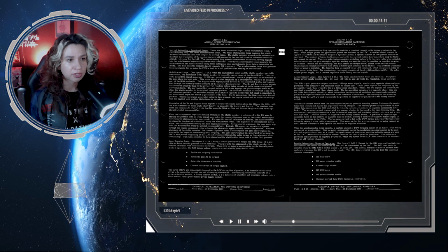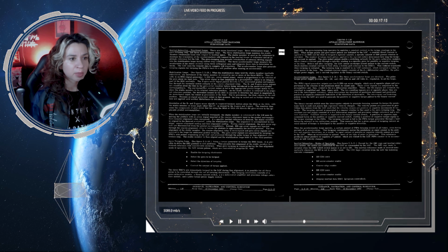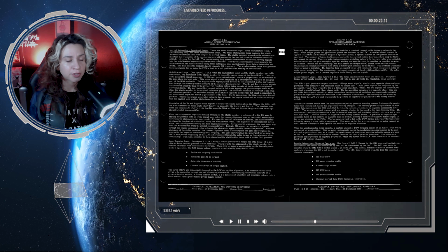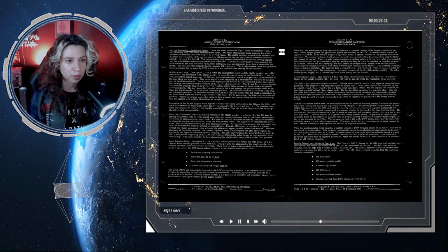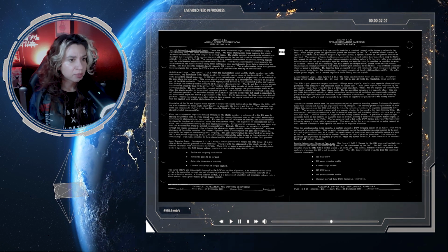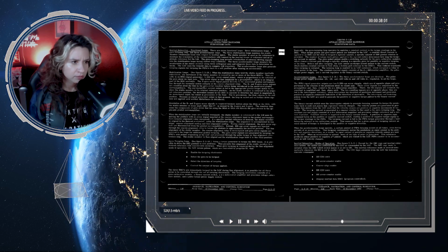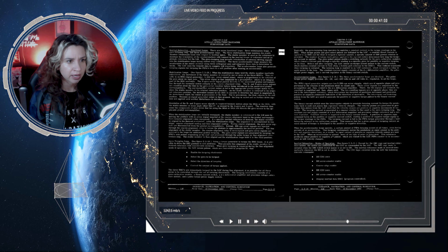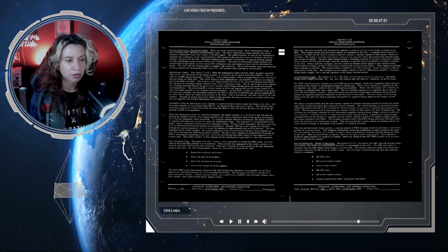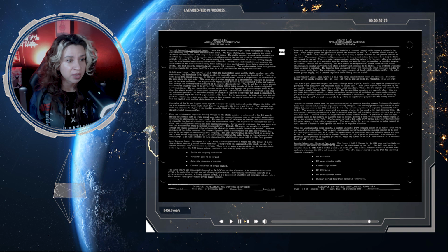The velocity pulses are generated by providing data pulses from the LGC, such that the velocity outputs are positive or negative increments of velocity. The torquing current is generated in a manner similar to that used in the gyro torquing loop. The constant current supply consists of an AC differential amplifier and a precision voltage reference and current regulator. Constant current is supplied to the binary current switch. A positive or negative input command turns on a positive or negative current switch, routing a positive or negative torque signal to the torque winding in the PIPA.